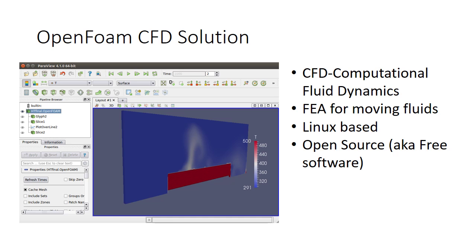For our specific model, you can see here, we modeled the flow over the space between just two of the fins, since the fins were repetitive throughout, and we wanted to simplify our model. As you can see, the red part there is the actual fin, and the blue is the air that goes around it.